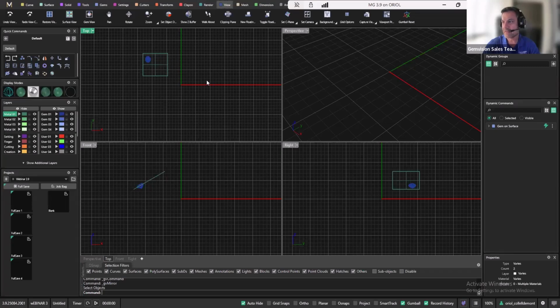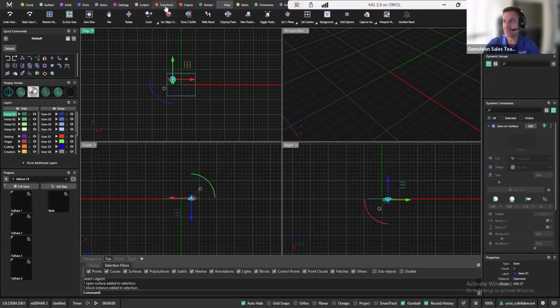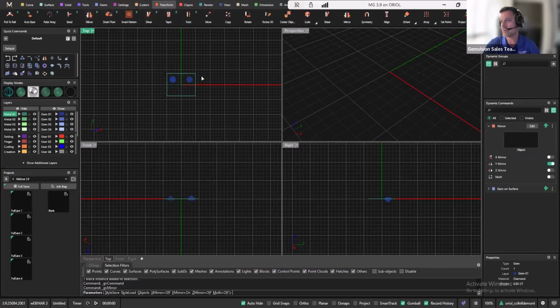And now, as you can see, I have this new view that is related to the surface that I had. Okay, let me just be sure. So first you need to select the surface, and now I move the plane to this surface. So now, as you can see, everything is looking to this surface. Now, because I moved the plane, I can select the stone, go to transform, and do the mirror, and it's doing the mirror exactly on this other side.